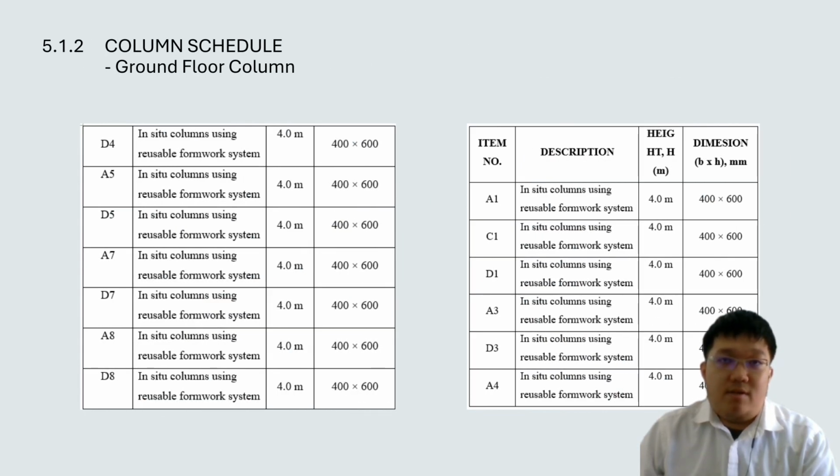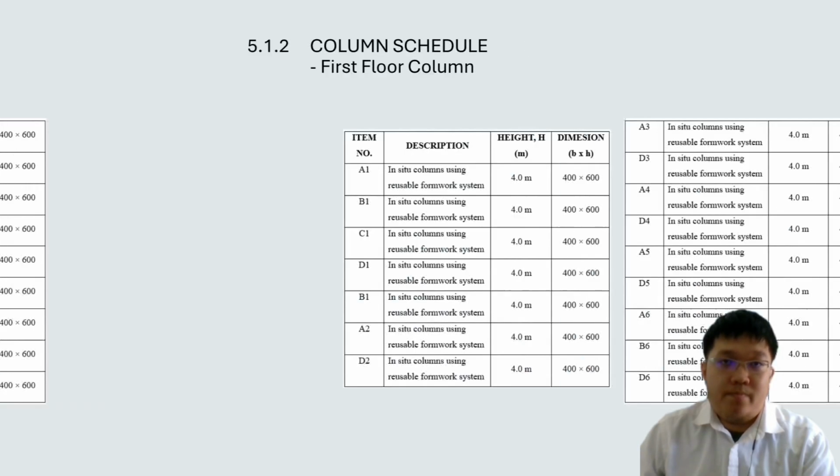The slide presents the ground floor column schedule. The columns are standardized in size and designed to support prefabrication and repetitive construction. Standardized column dimensions help reduce production costs and simplify site installation, contributing positively to the IBS score.